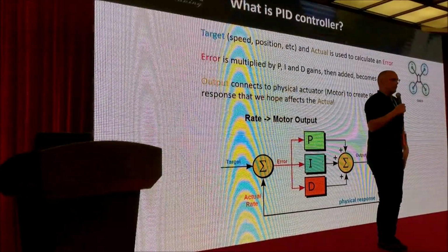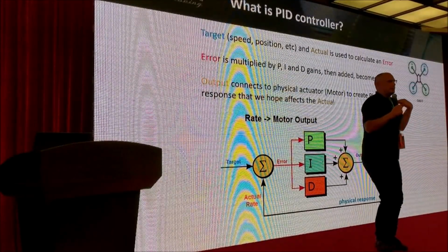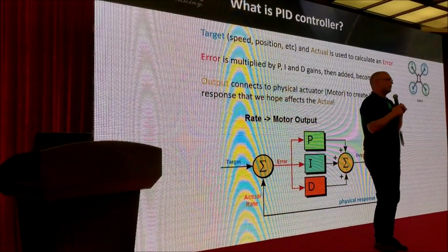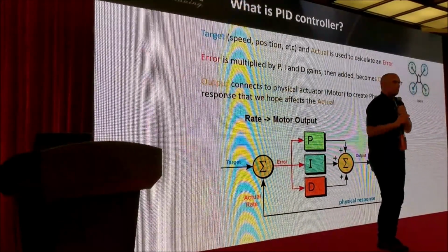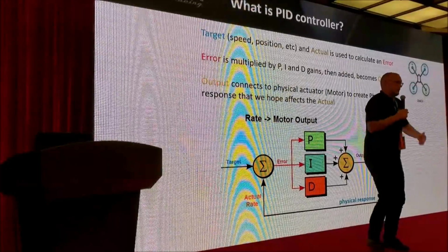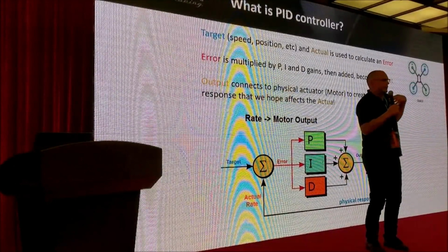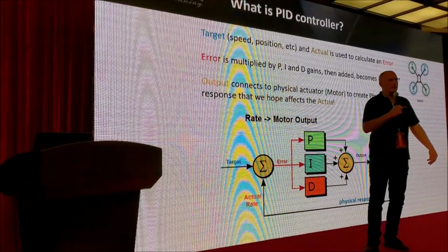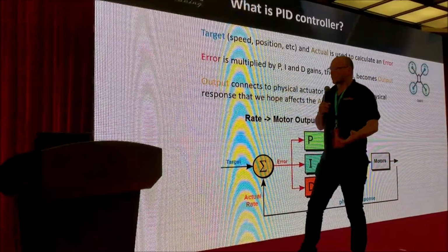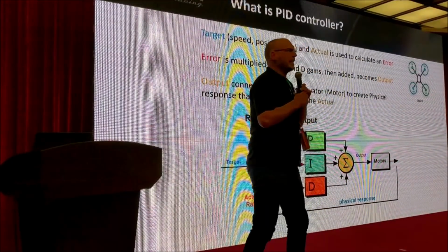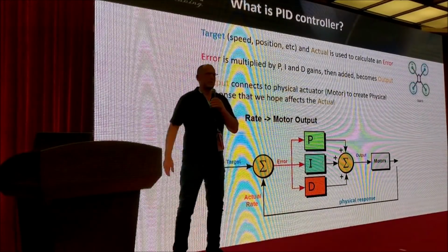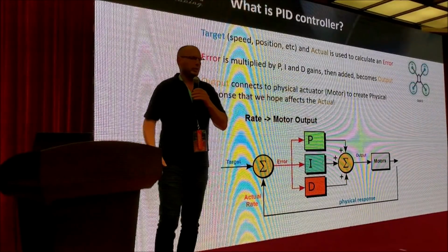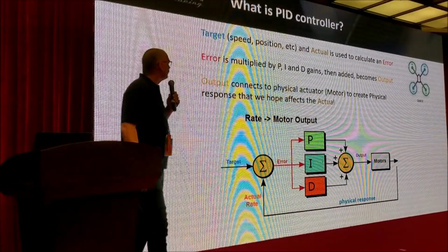If I'm standing on this spot and I get a push in this direction, the D term, even though the error is really small, will make me push back against it when somebody pushes me to the side. So the PID terms are a very natural and obvious way of dealing with a controller.